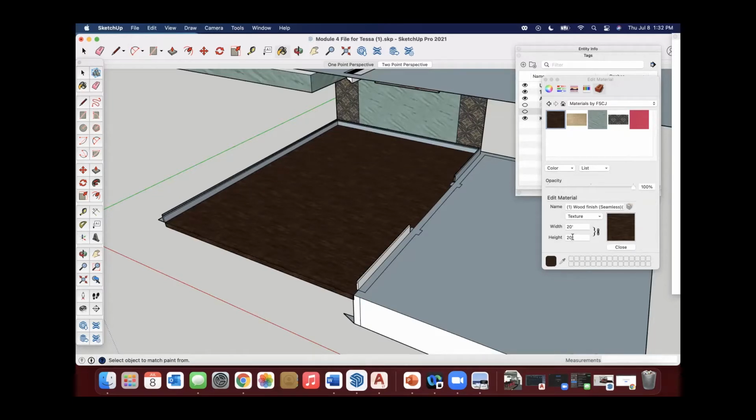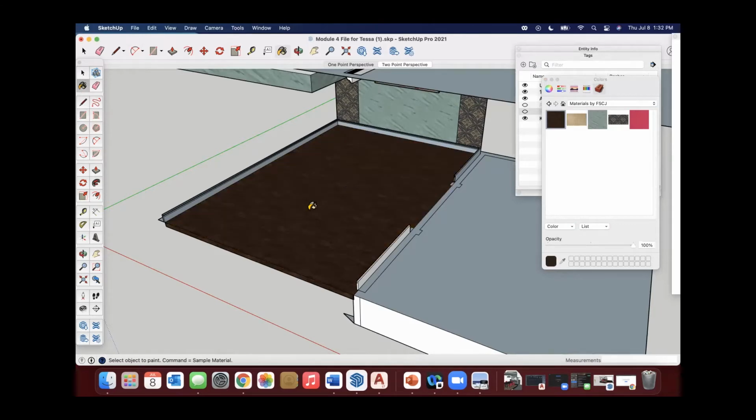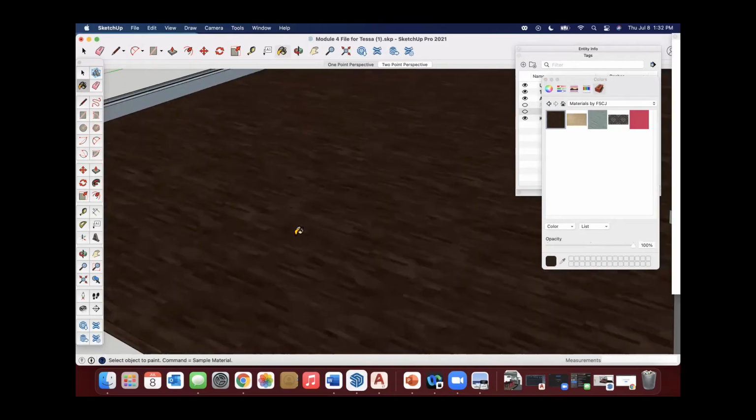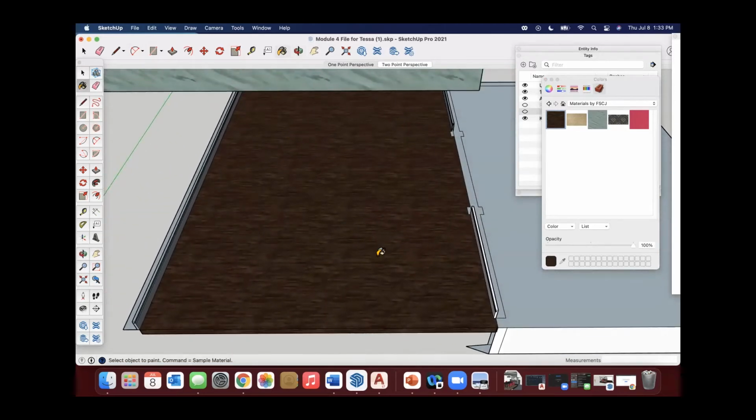If you run into this issue where you are in edit mode and you say 10 feet and select that, because we didn't change the aspect ratio, and we hit close, and then I try to modify that and apply and it doesn't change the scale, that's not great because you're like, oh, it's not working. So mine's not taking those adjustments for whatever reason.